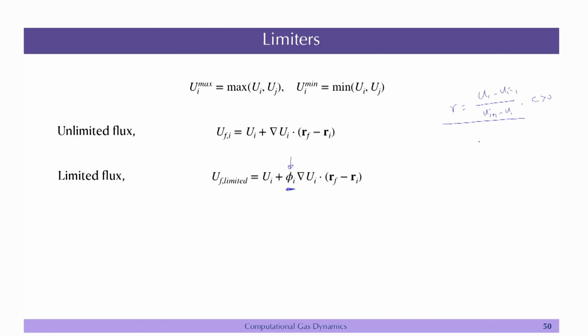That is, delta u of the upwind by delta u of the current, which is what we have been discussing. But that is not true in the case of an unstructured grid, because there is no i plus 1 and i minus 1 connectivity.